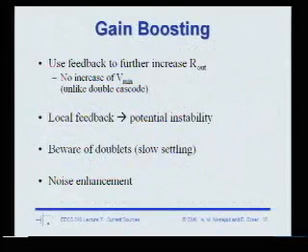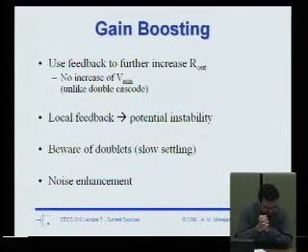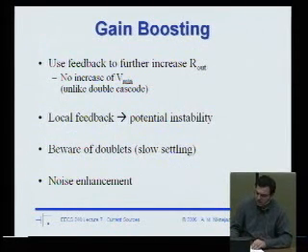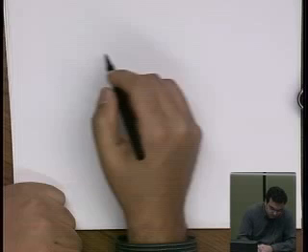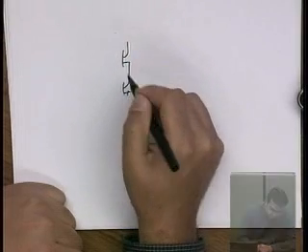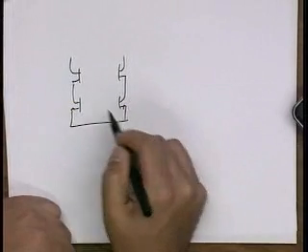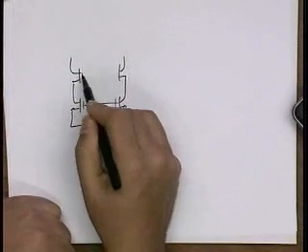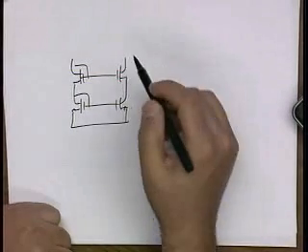Okay, so we talked about methods of designing a high impedance current source. One is a cascode. How do I get more impedance than a cascode, right? So I'll just draw a standard cascode, not a high swing version. Let's say this is not quite enough output impedance.